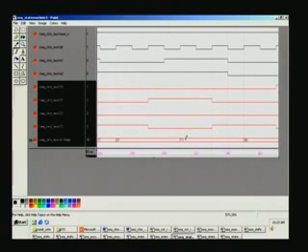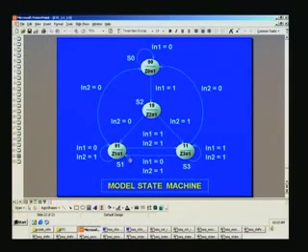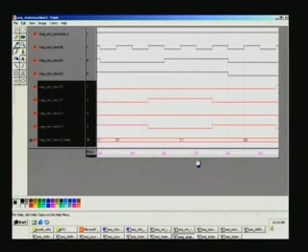In the 1-1 state, let us see what the input is here. In this case, both are 1, and we are in the 1-1 state. Let us see what happens there. We are in the 1-1 state, and both are 1. So it has to remain in the same 1-1 state. Is it remaining? What is happening here? It goes to Z3 only at the rising edge of the pulse here, right?